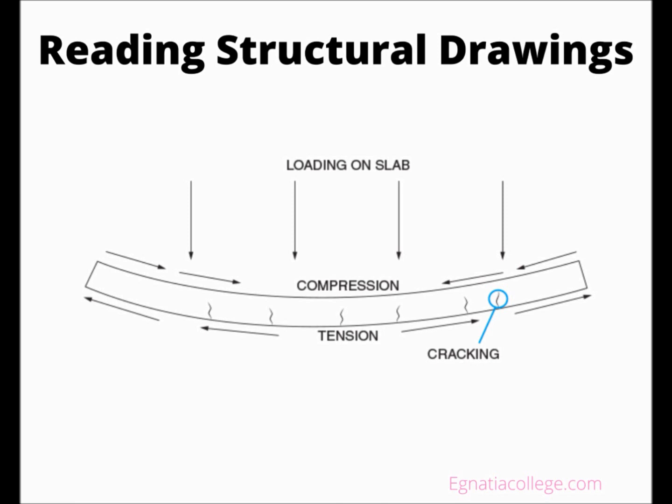Concrete is a very durable material and a good choice for building foundations. But it does have one drawback. While concrete is very strong in compression, it is weak in tension. Looking at the profile or elevation of a slab, the forces placed on the slab tend to make it deflect or bend, causing a compression face and a tension face.